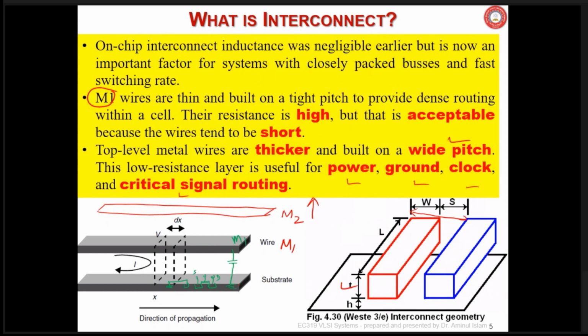Various lines will be there in the metal levels. This is the substrate or bottom level where you are going to make MOSFETs, as I have shown here, N plus region, etc., to make the N MOSFET, and in the N well the PMOS will be made.